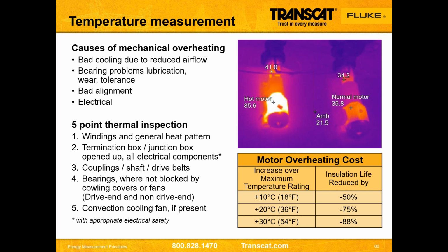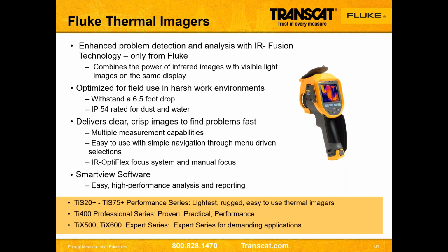So, why is it hot? Well, I don't have proper airflow across the cooling fins. It's not being properly lubricated. It's out of alignment. There's electrical unbalance. So the motor's drawing excessive amount of current on one of the 3 phases, and as a result of that, it's getting hot. So again, we're going to use the temperature piece as an indication of a future failure, but go measure with other tools to figure out the why. So again, we've talked about this already. Thermal imager, great tool. Certainly any number of choices we have to fit any size application or budget, depending on what you're trying to do.